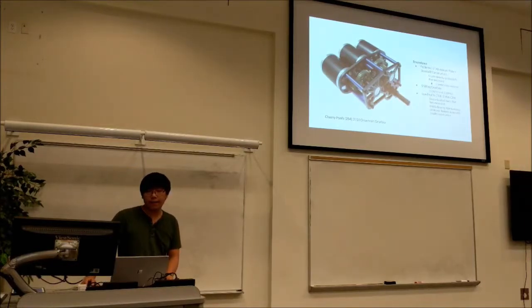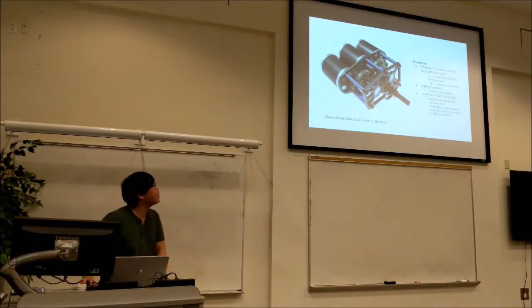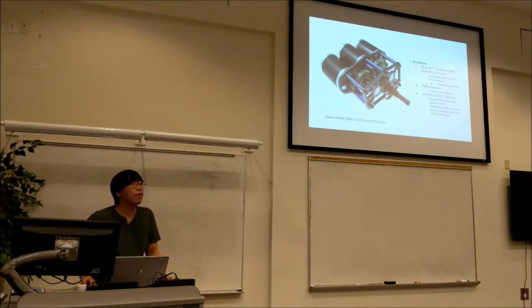And basically, it allows them to achieve this flat packaging. But typically, double loading the center pinion isn't really recommended just because it can break. What they did to counteract that is they put a secondary plate here with a bearing to reduce the cantilever on the motor. So basically, they were able to achieve this flat packaging without reducing the robustness of their gearbox.